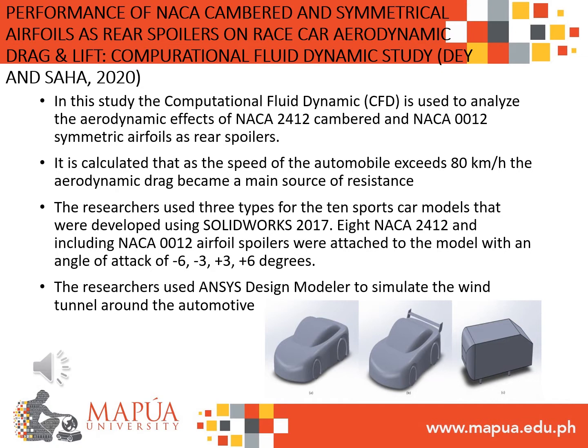The researchers used three types of the 10 sports car models that were developed using SolidWorks 2017. NACA 2412 and NACA 0012 airfoil spoilers were attached to the model with angles of attack of -6, -3, +3, and +6 degrees. The researchers used ANSYS Design Modeler to simulate the wind tunnel around the automobile.